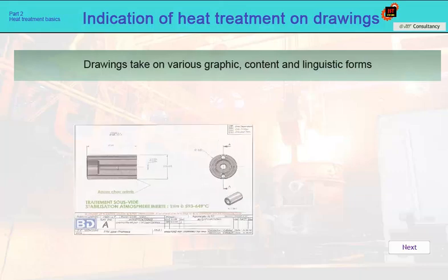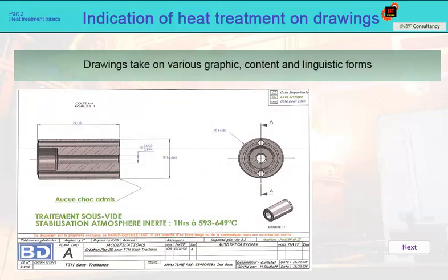Another example is a French drawing for a part made of Fe-Si 3P material. In the literature, it can be found that it is a material complying with EN standard 1.3843. It does not occur in the lists of steels. After a long search, it is possible to find out that it is steel alloyed only with silicon with a content of 2.5 to 4% silicon. However, it is equally difficult to trace the conditions of heat treatment.